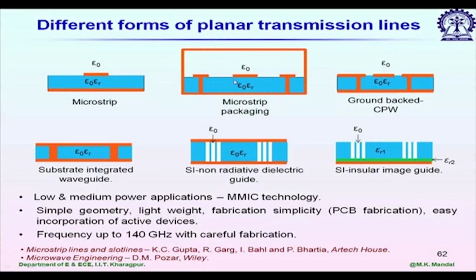So, microstrip line it is placed inside a rectangular pipe like structure, and you can see left and right side we have that arrangement to suppress TM0 mode. You can identify the strip and the grounded via, which will suppress that perpendicular electric field component. Similarly, right side we have ground backed CPW. This is shown without any packaging scheme. We will learn later. We have also PCB form of rectangular waveguide.